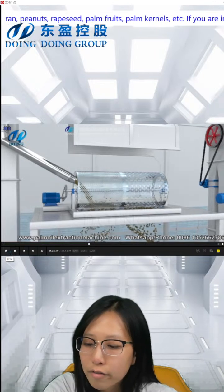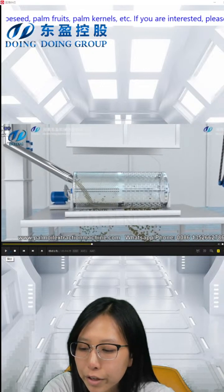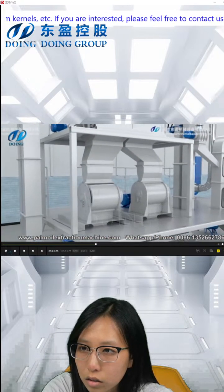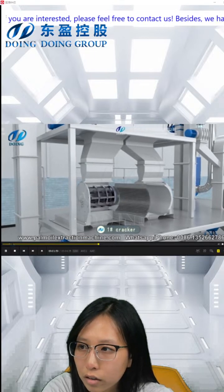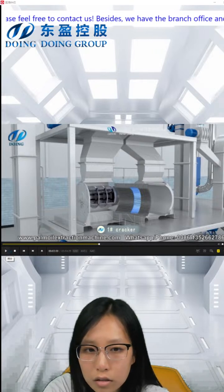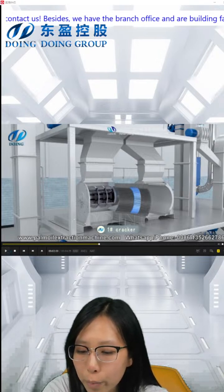Through the size of the machine surface, it classifies the palm kernel, respectively, into 2 crackers. Yes, cracker. This is the cracker, different 2 crackers. Why do we use 2 crackers? Because the palm kernel volume for the same cracker is similar.